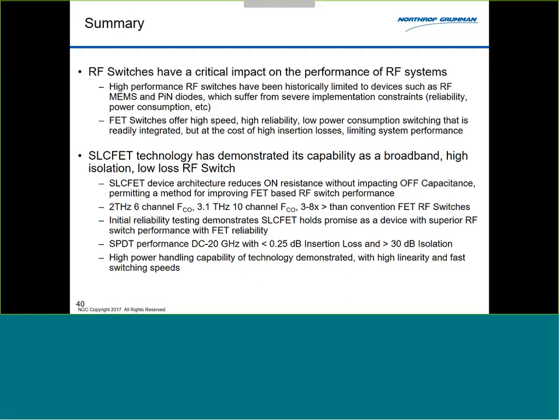Well, I had mentioned before in the talk that the device is a quasi-buried channel device, and that's actually true. In your normal device, all your carriers are just a few nanometers away from that interface. In this device, that's actually not the case. Most of the carriers are tens of nanometers away from any of those surface interfaces. So that does lessen that impact.